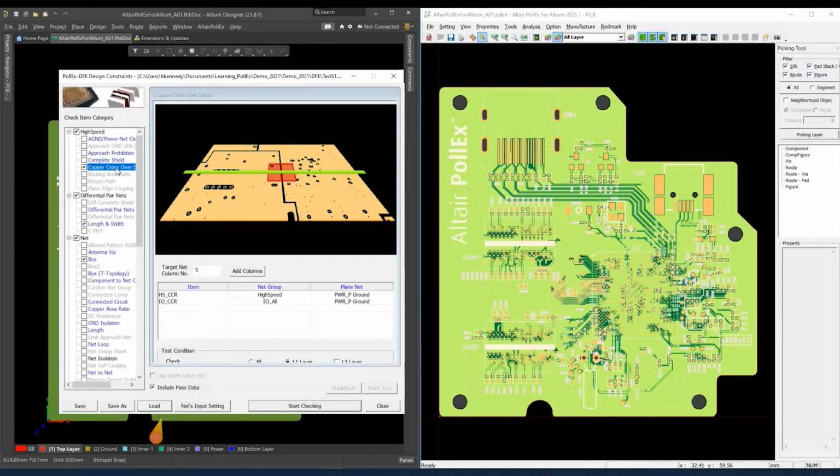In this example, I'll be checking a few areas. One being the copper crossover, looking at if there are different traces that go over different copper planes, and understanding the differences between the impedances as it transfers over from one plane to another.